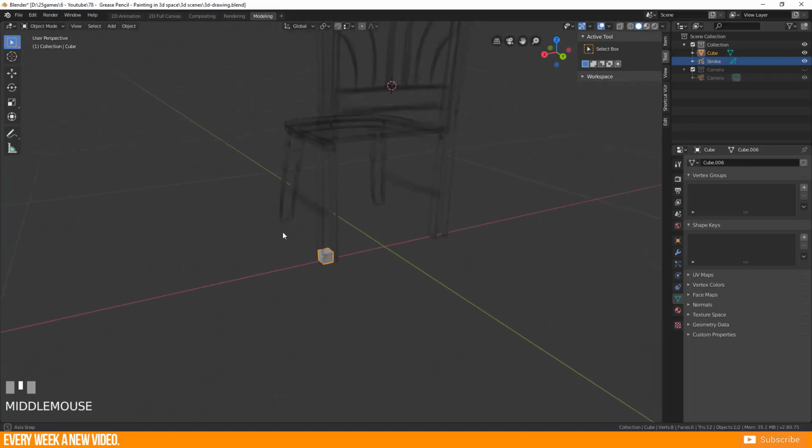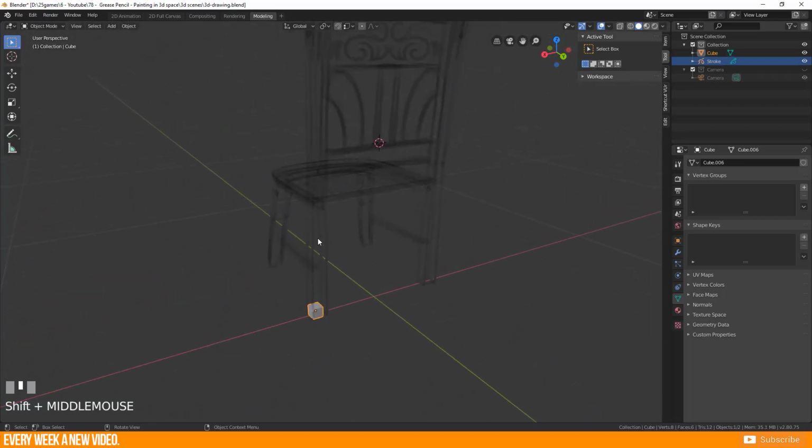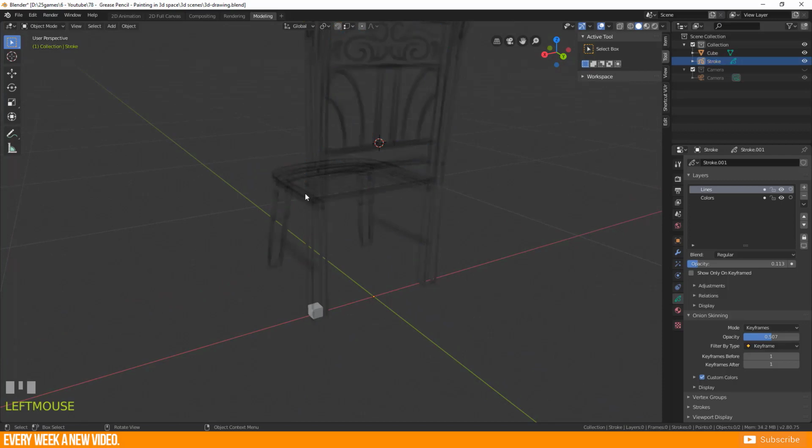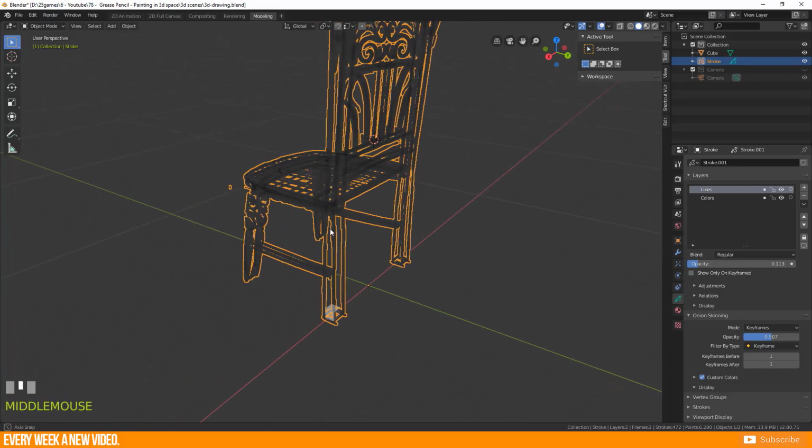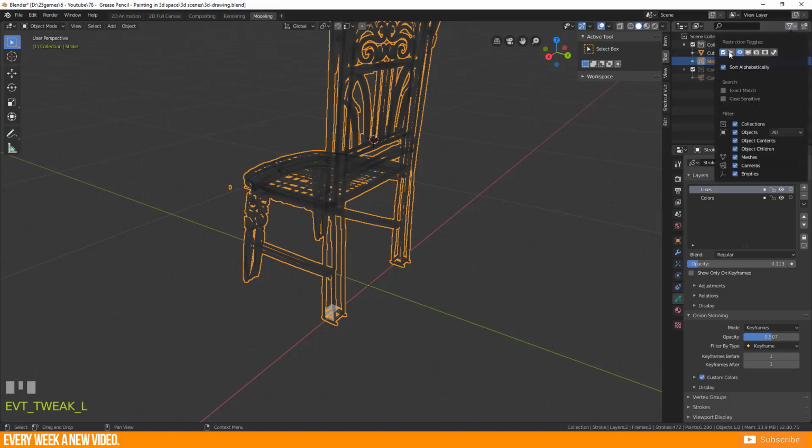Very important, because I saw it already: it is very annoying if we want to select the cube and then our sketch will be selected as well. And I don't want to select this at all while modeling. So I want to lock it, and we find this when we click here on filter and enable the selectable object option as well.